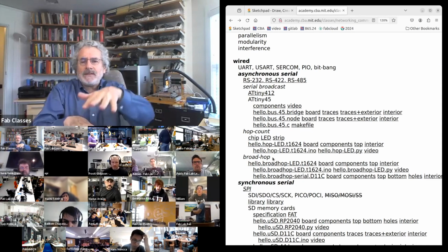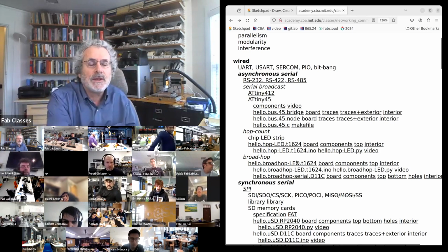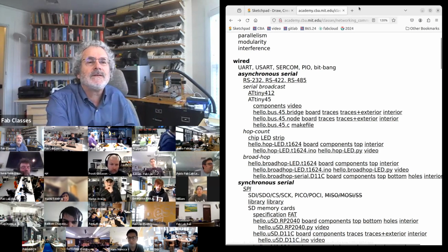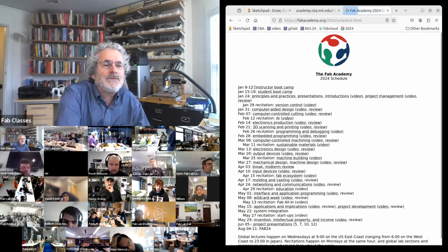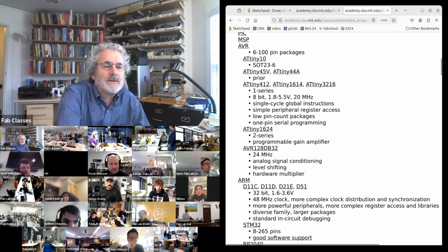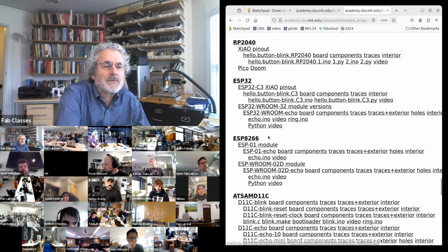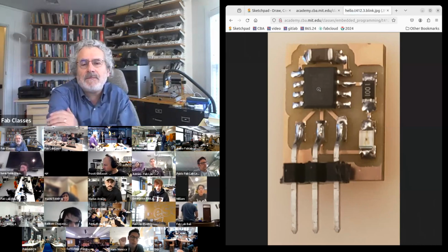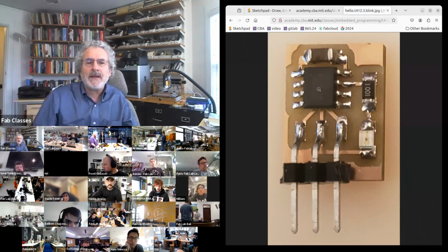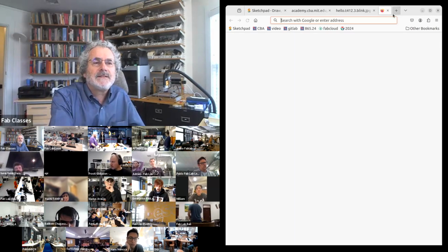If you want to make the lamp with the stacking layers or the environmental sensors with the modules, you put a little processor in each node. And as a reminder for the processors, don't forget our friend, the tiny 412. The tiny 412 is a 15-cent 8-pin processor, and you can get these in even much tinier packages if you need it.